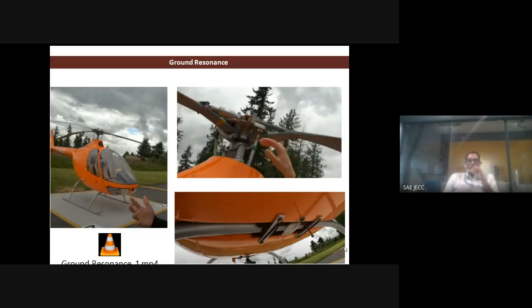Once you look from the bottom side, you can see some dampers here, and also some dampers in this region, because it is allowing some fluctuation, so that instead of maintaining a consistent orientation, it is just changing it intentionally, so that the resonance is avoided. The testing of this ground resonance in a real situation, the experimental part, I will show you after this presentation.